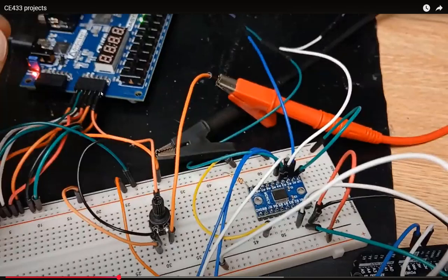All right, and these are the inputs. So I grounded the minus input. It's a differential input, so I grounded the minus input. And I'm connecting this one, the plus input of the ADC, to the output of the potentiometer. Okay, and this is the connection I have on the desk right now, and apparently it works.